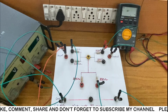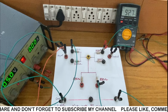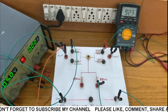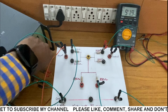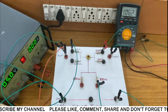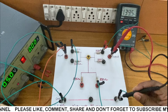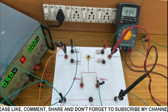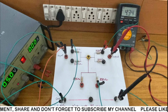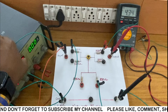We have to make the DC regulator on. So I am making the circuit on. So let's look at what I have to do. I have to connect the multimeter in between the output and the ground, and I'm going to measure the voltage. You can see here it is 4.4 volt DC voltage, so we can see it is a VTH, Thevenin voltage.